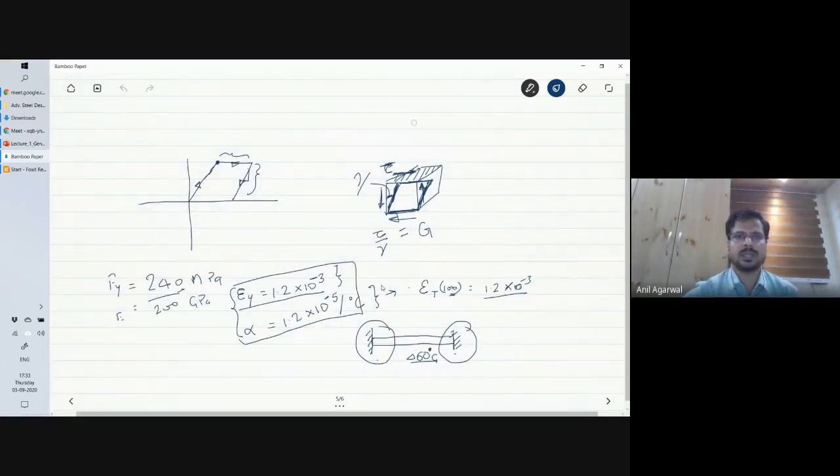What I was saying is that this is the elastic part and this is the plastic part in the stress strain plot. This is the strain and this is stress on the vertical axis. This is the elastic part, this is the plastic part, and this is again unloading, which is also elastic. Whatever plastic strains you had get accumulated, but unloading itself is elastic. So for these deformations, your Poisson's ratio should be 0.3, but for these deformations, your Poisson's ratio should be 0.5.